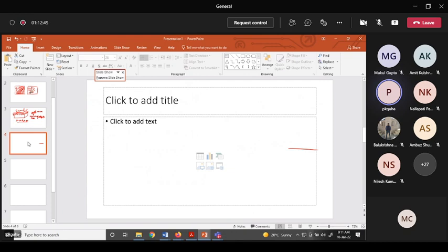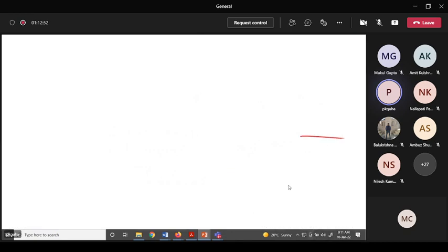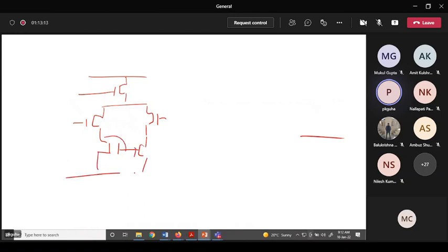You all know that in case of an op amp maybe you have a biasing transistor, and you have like two transistors, and then this is a current source, and so on and so forth. Okay, so say this is VDD and ground, right? This is just an example coming to the top of my head now. So you see there are three transistors between rail to rail. So you have to make sure all these transistors are in the saturation region.